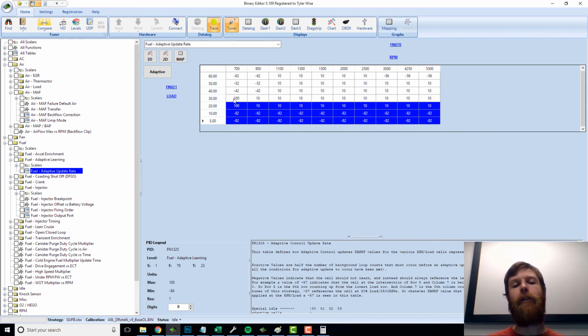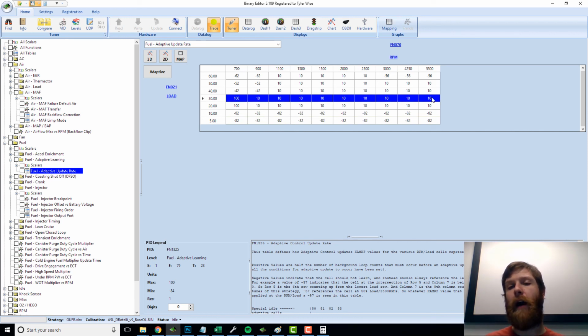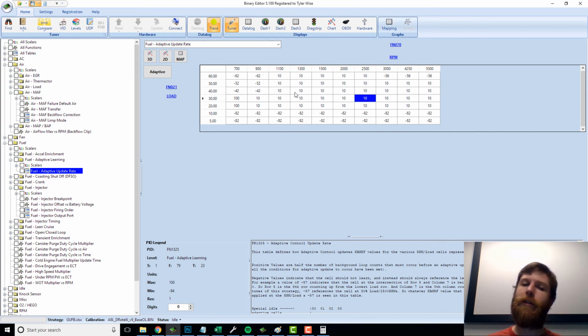But to do the others, you'll actually have to be driving the car. So again, usually what I'll do, in a 5-speed car, I'll focus on my shift points, get into some area where I have no traffic, and try to stay at a very specific load, which will probably be a little bit higher. I'll try to hold it at some different RPMs, probably up to about 2,500. And then I'll try to stay at a heavier throttle, which, yeah, I'll probably be accelerating, but that way I can at least hold these different cells.